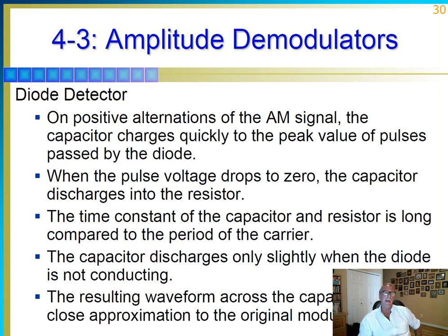And as we saw in our lab, we experimented with different capacitors, and the lower capacitance caused a lot more carrier bleed through, right? The demodulated signal was fuzzier, and that was carrier bleed through. We beefed up the capacitance, and that resulted in a better looking demodulated signal, although some of the high frequency components of the modulated waveform were attenuated by that capacitor as well. So we've got to get a happy medium.